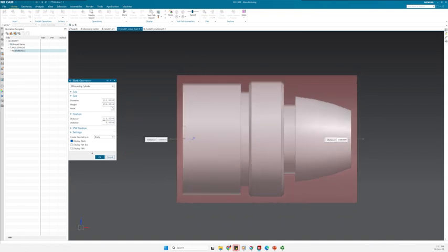And the next thing that we need to define is these distances. This distance plus is the distance after your part from this axis. So this is something that I will define. For example, 3 millimeter is enough so that I will have a facing there. And then the remaining 7 millimeter would be, for example, here, or I can see that maybe it's a little bit too little for clamping. So I will just increase the height here, for example, to 160. And then again, I will correct this value to be 3. And now it's perhaps fine.